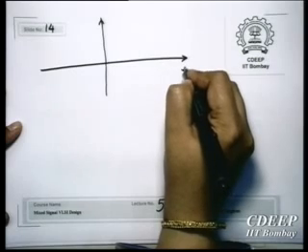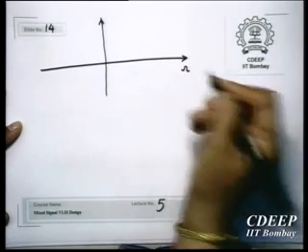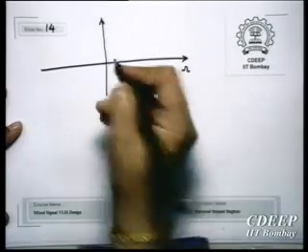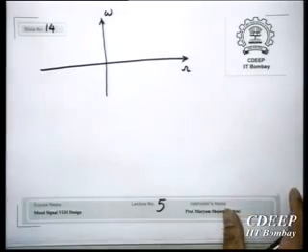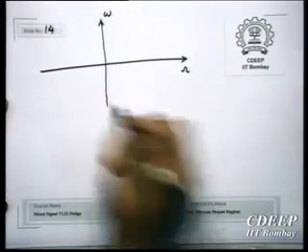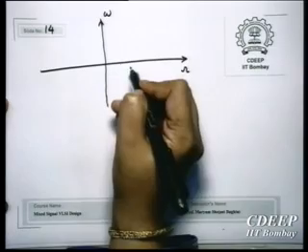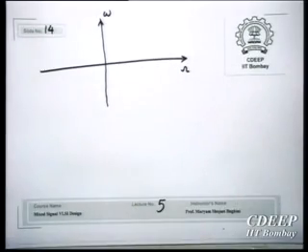Suppose this is omega. I show the normalized value by capital omega, and this is the real omega I want to get. When we are talking about a low pass filter, everything was normalized to frequencies between 0 and 1. Therefore, if I want to get a band pass filter, it's enough if I map my band into this band.